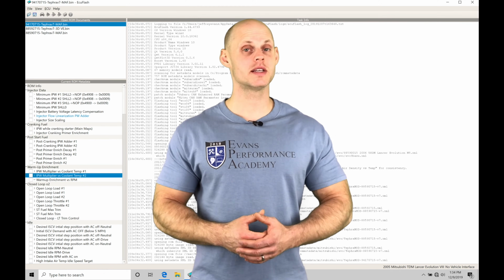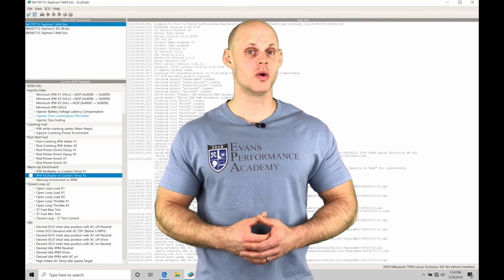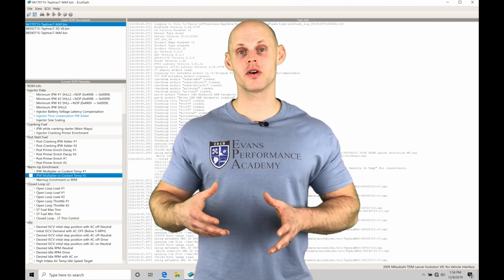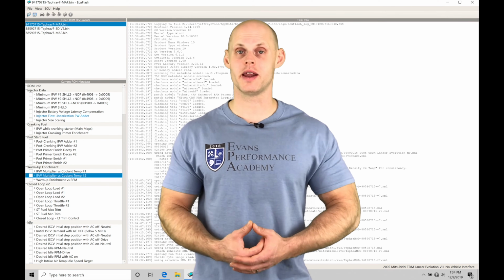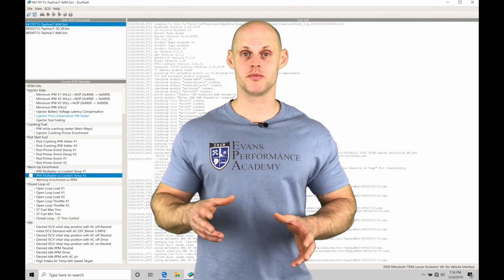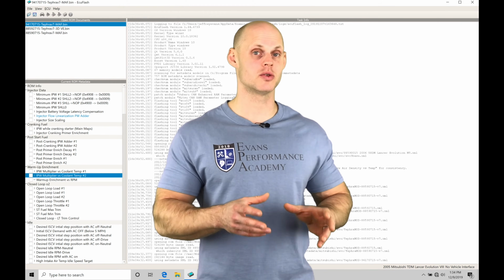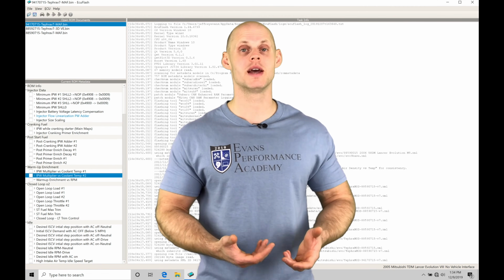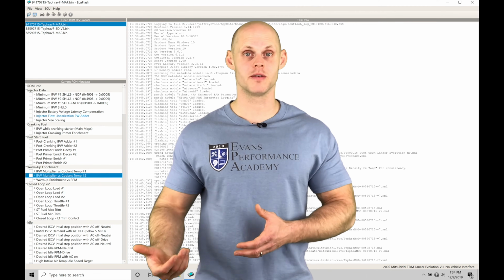In this video, we're going to take a look at working with our idle control. We're going to find that we have several different tables associated with our idle control in our Evo 8 and Evo 9 applications. We're going to have our virtual programming side of things, where we're programming our spark timing and our actual idle control stepper motor to achieve a certain amount of airflow and spark timing to hit the desired RPM we'd like for our idle.